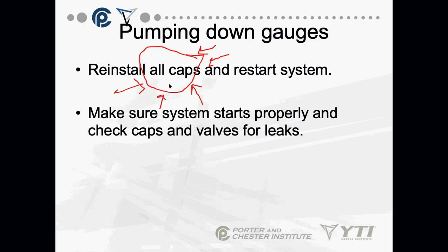Refrigerant can leak or release? Yeah, you can have little leaks because there's a little rubber gasket in that Schrader valve that wears out. But there are a few other reasons, too, that are very important.